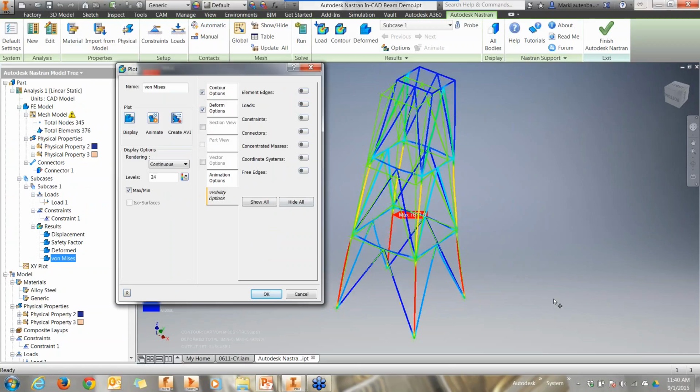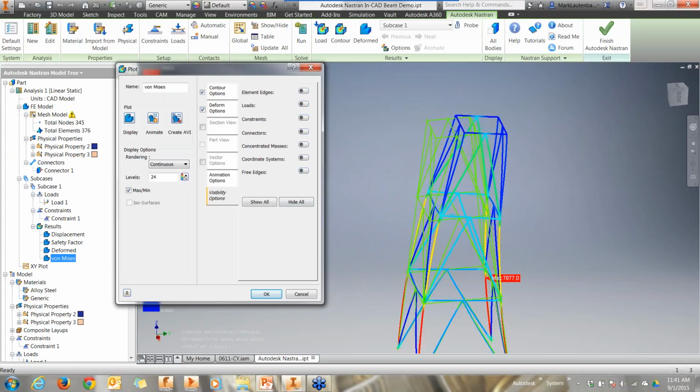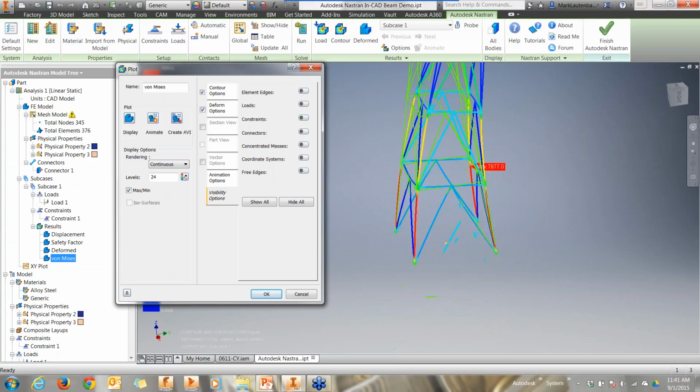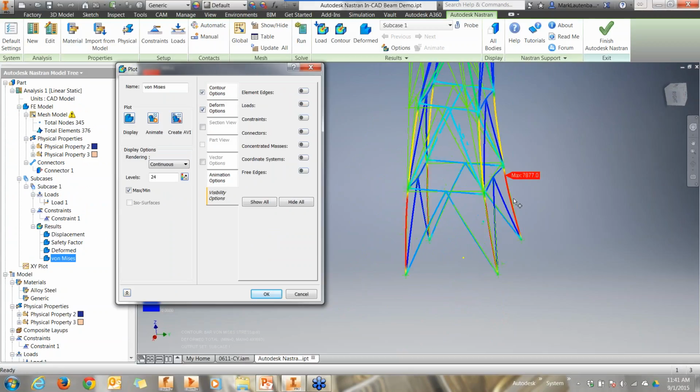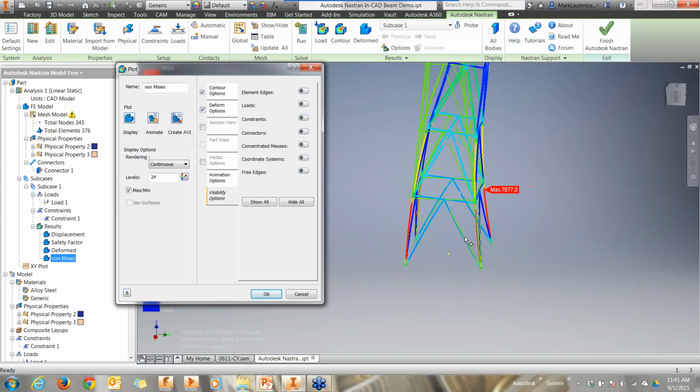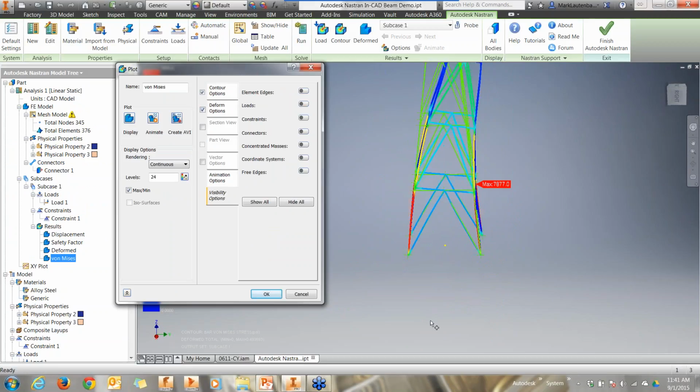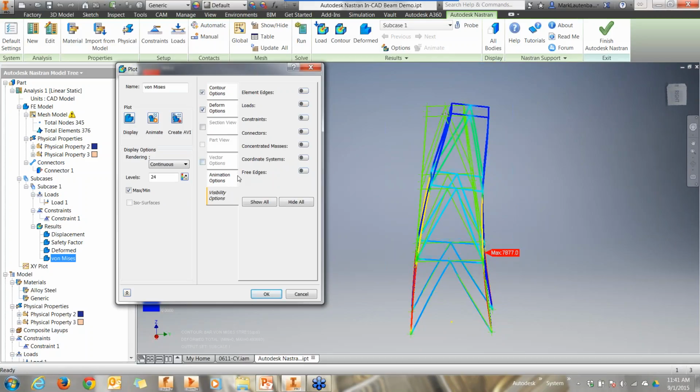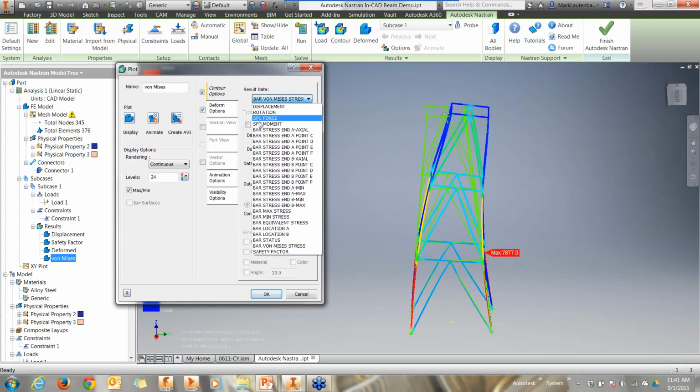And just by looking at stresses, we're not going to know whether, down here, this bar is going to buckle because of that. Well, with basic stresses, probably not. Maybe I want to look at compressive stresses.